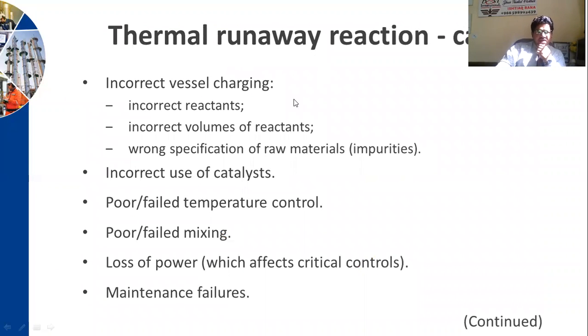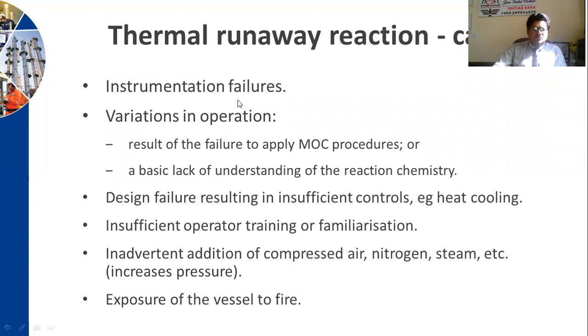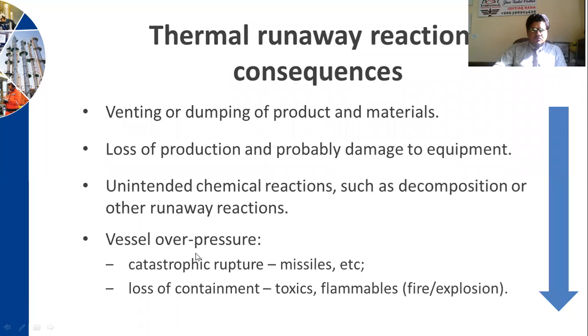Now, what causes thermal runaway reactions? Incorrect vessel charging, incorrect reactants, incorrect volumes of reactants. Wrong specification of raw material, impurities also cause this runaway reaction, especially the thermal. Failed mixing or failed temperature control, loss of power, maintenance failure, instrumentation failure, variation in operation, design failure, insufficient operator training, inadvertent addition or exposure of the vessel to fire.